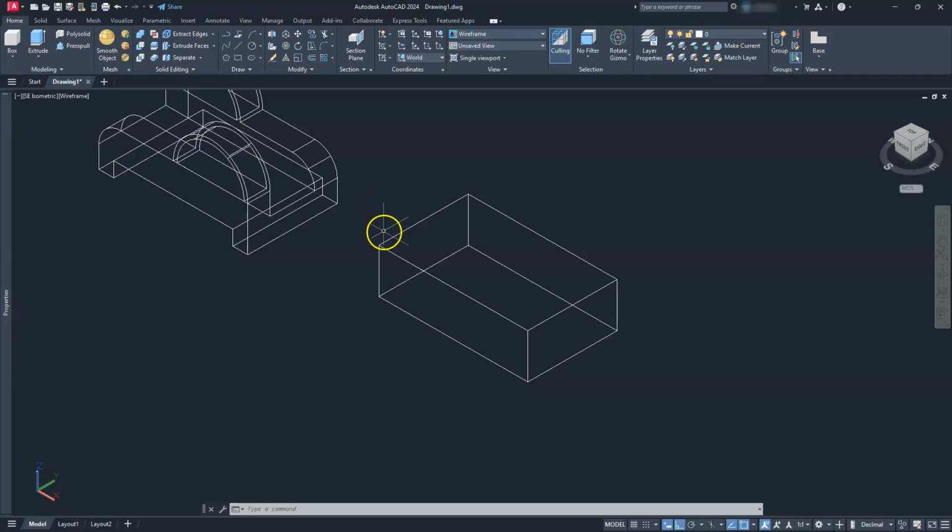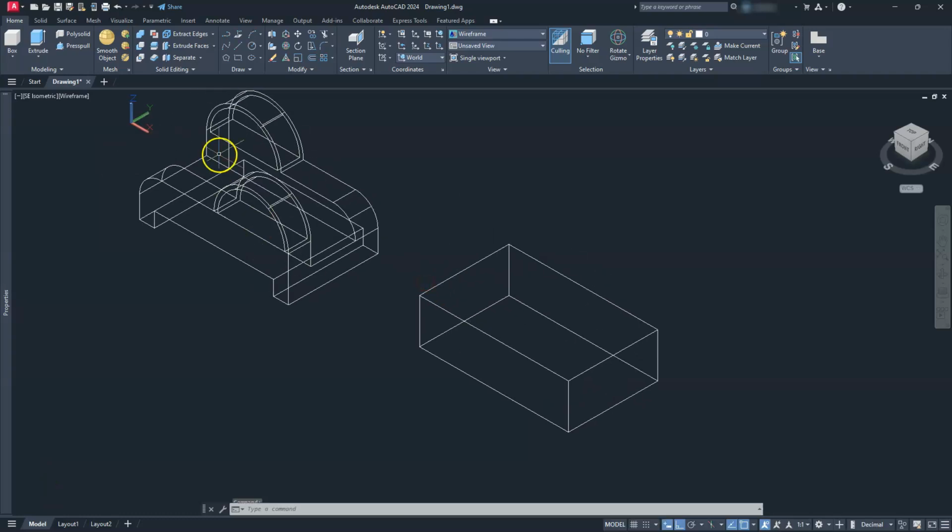There's a couple of different ways to do this, and I'm going to give them to you both ways. So you can see that I want my X and Y. The X is in the right direction. The Y I want going straight up, in line with this leg here, and I want the Z pointing this direction. We can use what we did before, or we can use the flip handles. You can imagine that if you're grabbing the X axis and then spinning it on that X axis, that's what these flip handles are for. So you can grab whichever axis you want and manipulate it off of that.